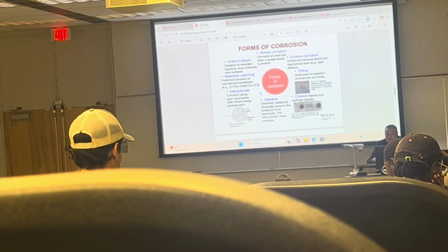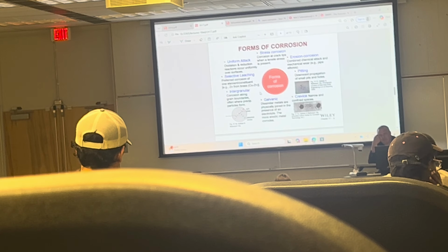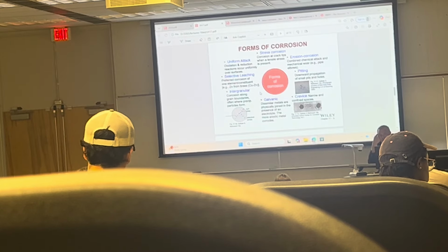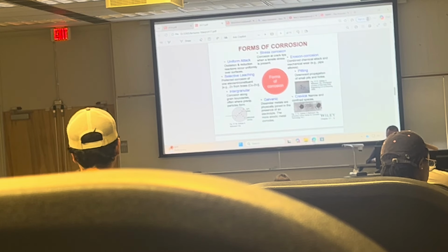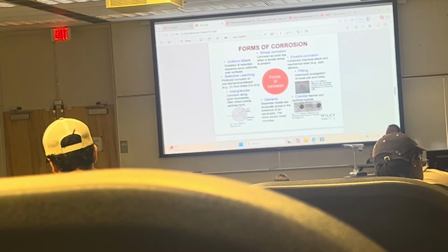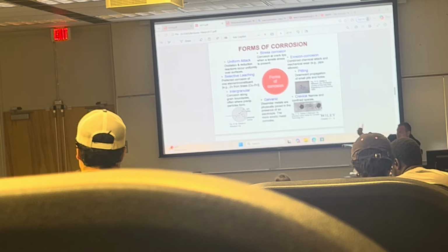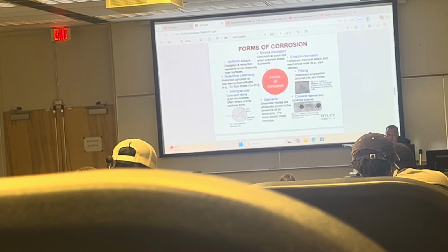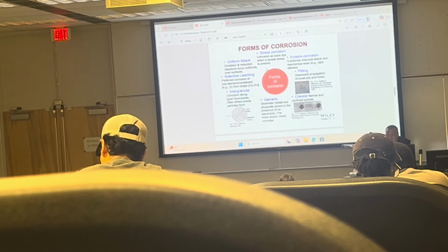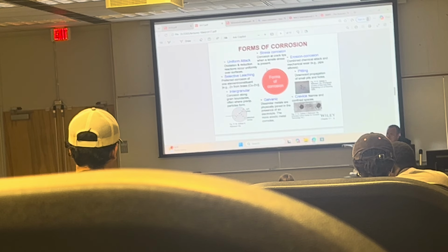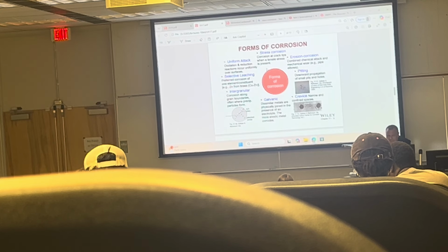Okay. The other one that we actually use in microscopy is called intergranular corrosion. And it happens along the grain boundaries because there's high energy associated with grain boundaries, and they get attacked first. So the removal rate of the material at the grain boundaries is higher, which allows us to have better contrast when you watch this in the optical microscope. Stress corrosion. This is when there's a combination of corrosion and externally applied stress where the structure is under load.